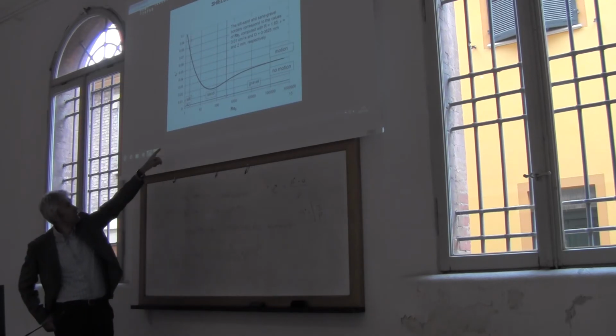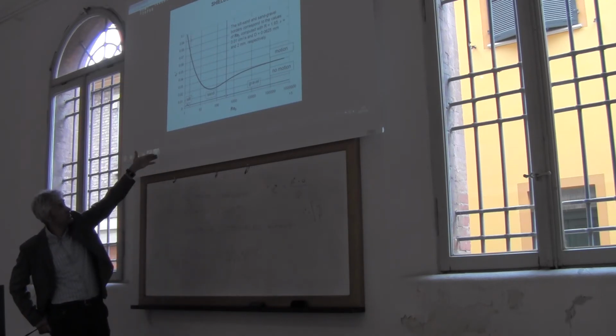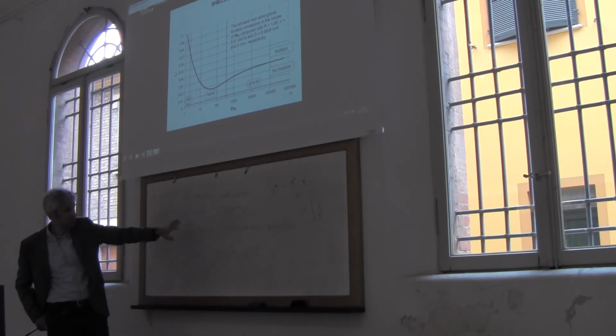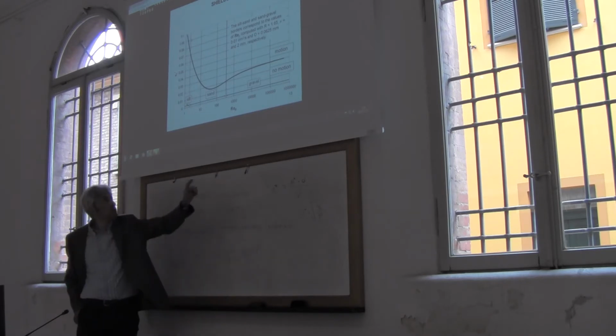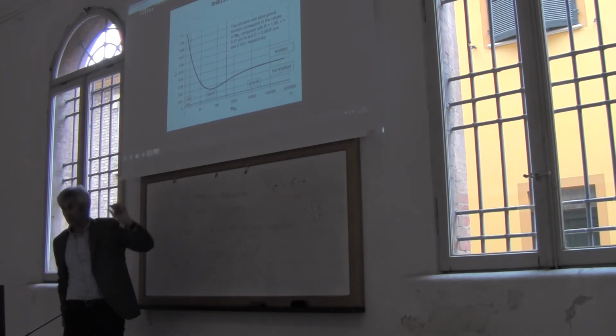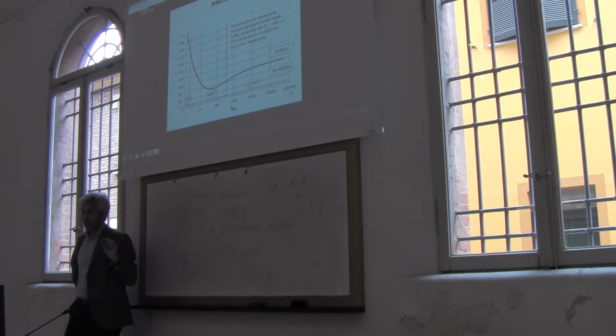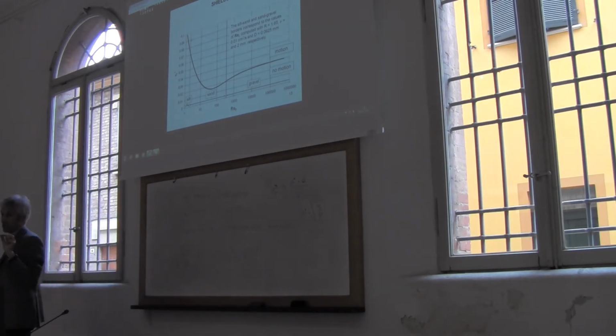And for low velocities, low values of the Reynolds number, there is a behavior that is like that. And what is depicted here? It's depicted the relationship and the equilibrium between the Shields parameter and the Reynolds number. So the bold line, the thick line, identifies equilibrium conditions.